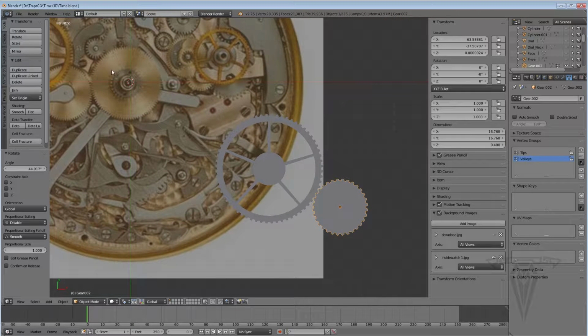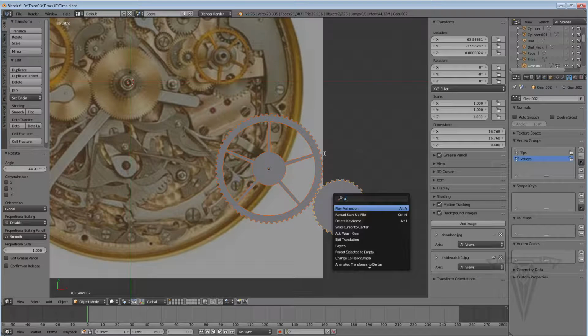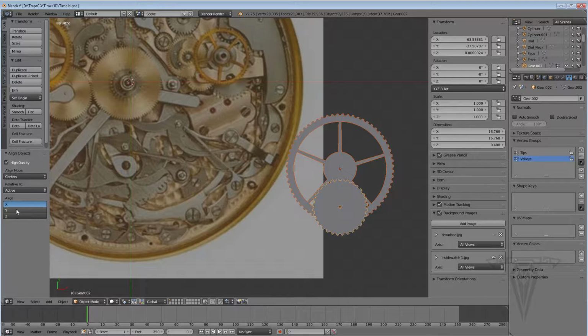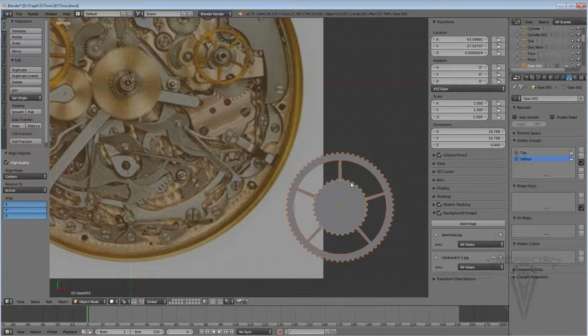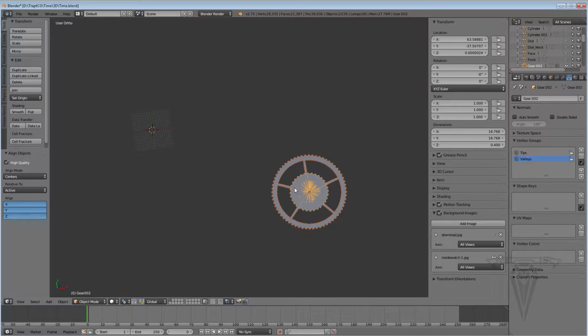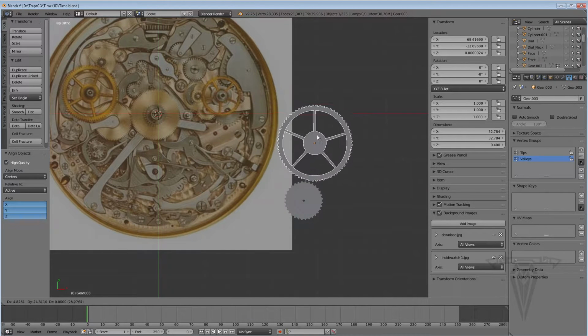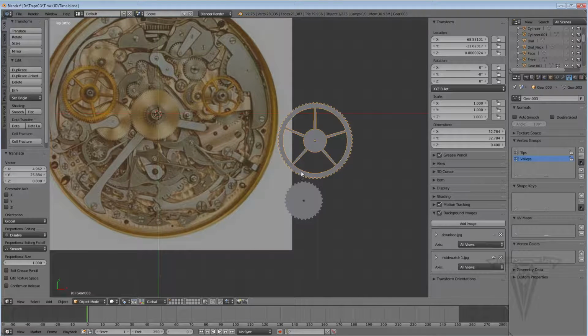Let's say like this gear has a gear right on top of it. So let's say I modeled out both. I can actually come in here, let's say it's these 2, select this guy, shift select this guy. I'm going to go spacebar menu, type in align objects. It's going to give me the menu over here. All I have to do is click on whether it's going to be X, and I hold down shift and click on the rest. And you can see here it aligns them correctly, and then I can position them how I want with each other. So let me go back to my top view. Just to tell you that the spacebar menu is very useful, allows you to pretty much find anything. The stuff that we were pulling up over here can be applied to the spacebar menu.